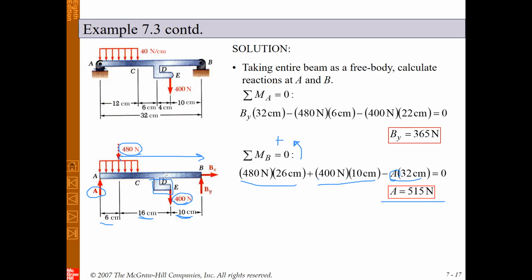You know, if you plot this arm, we will have the free body diagram for this arm. We will have one 400 Newton force here, and we will have one reaction here at this point D, for example, we can call it D, and also we will have one moment. This we call MD. You can calculate D. D is clearly equal to 400, and MD, of course, the direction must be in this direction, not this. It should be counterclockwise.